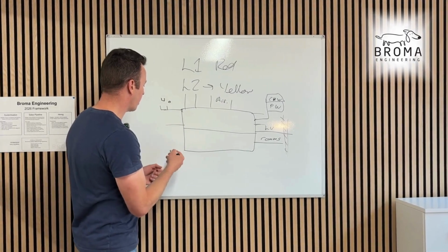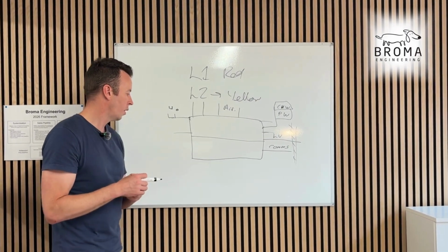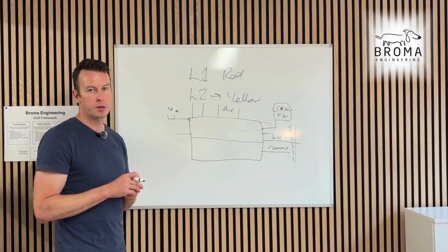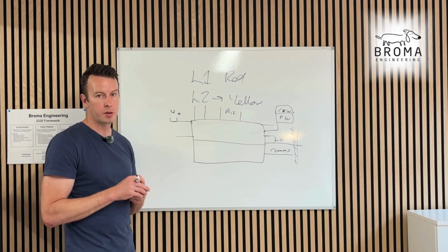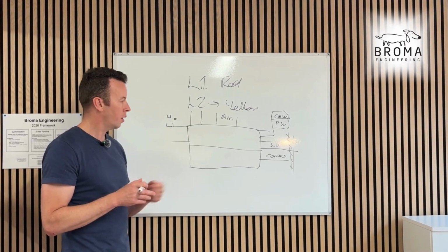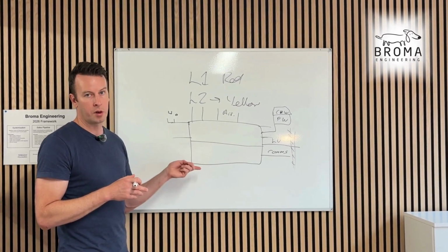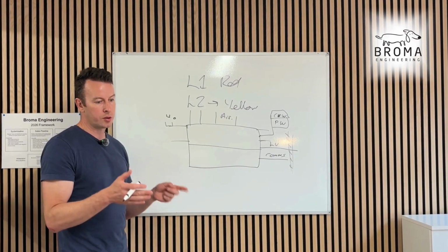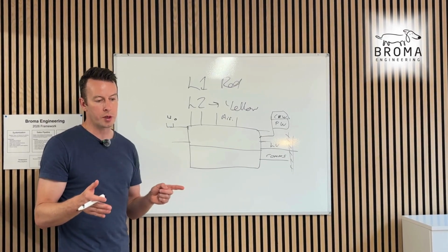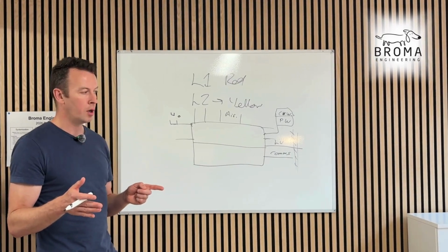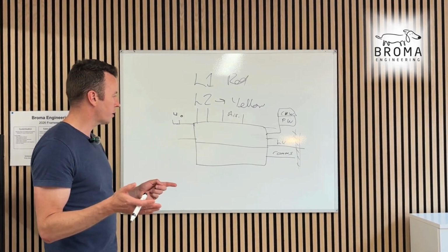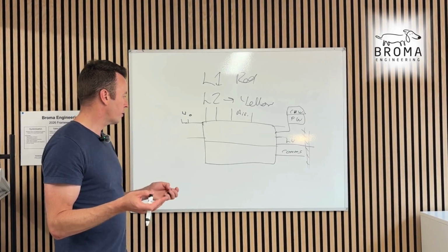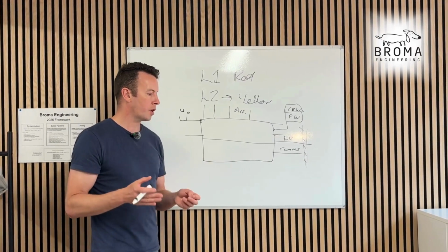Also, the pipework, I would get it approved before installing. Sometimes pipework can be in precarious positions when going into these AHUs, and you don't want people having an opinion on it at the end for the quality inspections. At the end of level 2, you want this signed off, highlighted, a BIM review and the federated model saying this is the way the pipework's going to be. We've designed it as best we can so it's not going to get damaged long term. It's easy to maintain for operations. If it does get damaged, it'll be easy to replace. All that good stuff. And make sure that that's covered.